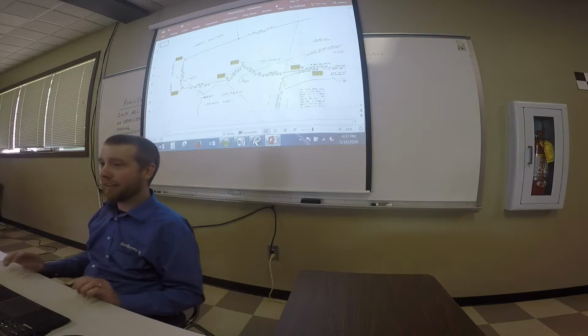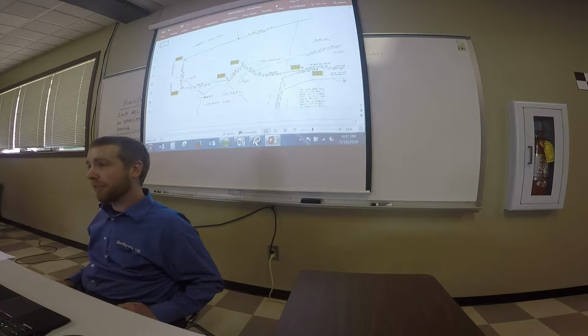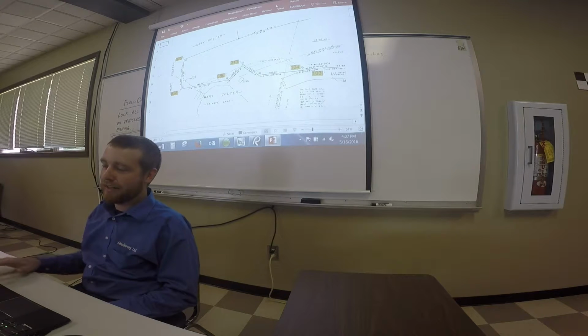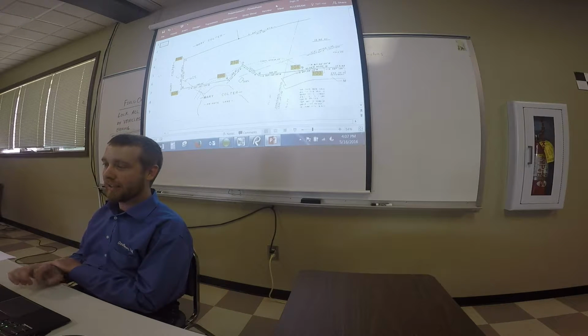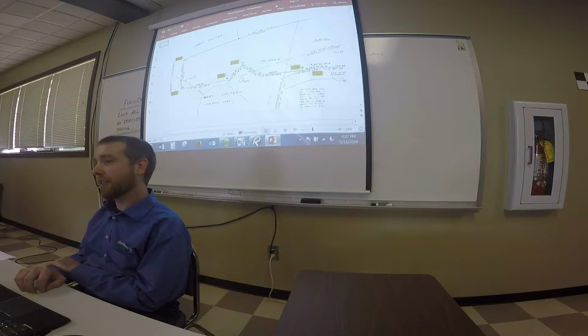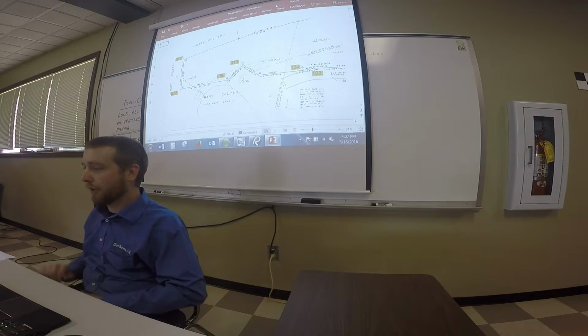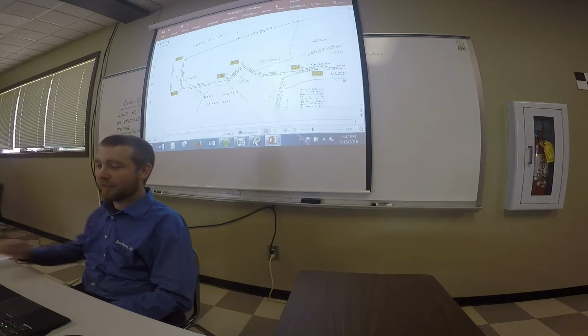Today what we're going to talk about is how to find pins using the data collector. We're going to talk about how to turn angles and distances. We're going to talk about how to find the angle between 2 points, between 3 points. Then we're going to try doing distance intersection to find a point. And lastly, we're going to run through how to do rotate and translate.